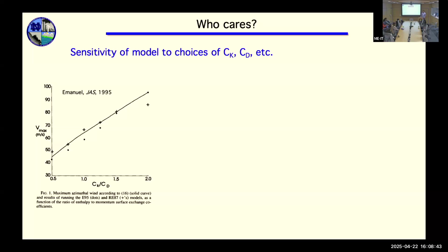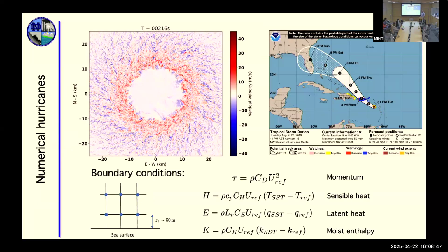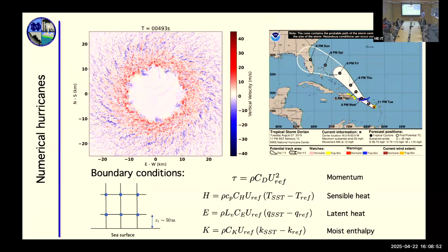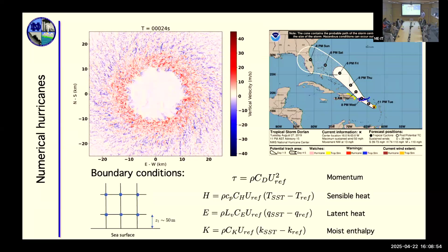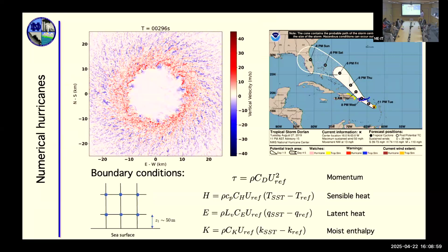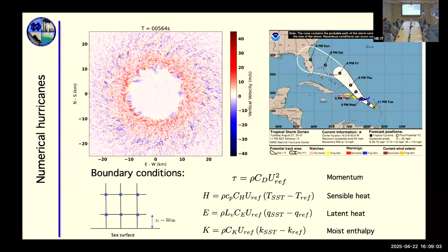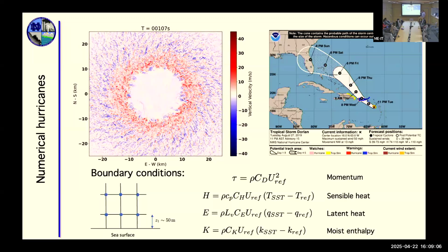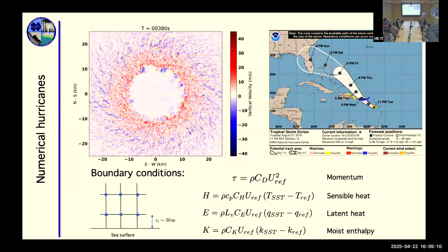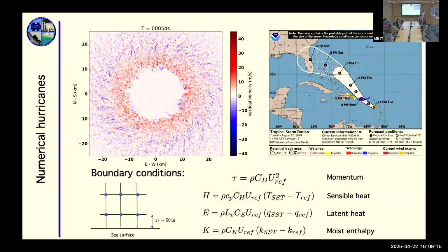So those parameters on the previous slide, would those go into a wall model based on a law of the wall or something? Yep. Yeah, they don't call it that, but yes, it's a wall model. Okay, and so you usually presume some boundary layer profile for not only momentum but for the temperature and energy. Sort of, but you have to realize that for something like this, there is no boundary layer resolved. The first grid point might be well above 500 meters, and so you might not even be resolving anything. So you have a boundary layer scheme in addition to.